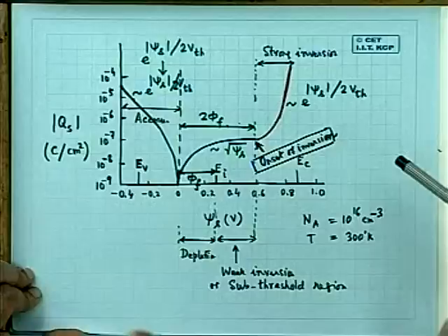This consists of exponential terms containing e to the power psi s divided by VTH, 2 VTH, plus minus etc., as you remember. And then CD, what is it called? It's called dynamic surface capacitance per unit area. Again, everything per unit area. That is why the unit is farad per centimeter square. So this expression we derived, and you can calculate the value of CD for different values of psi s straightforwardly using this equation. There is absolutely no problem for you.